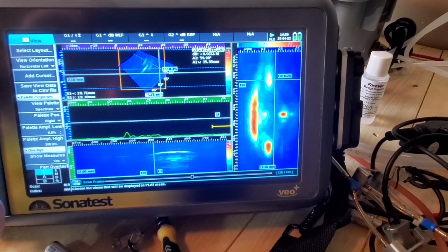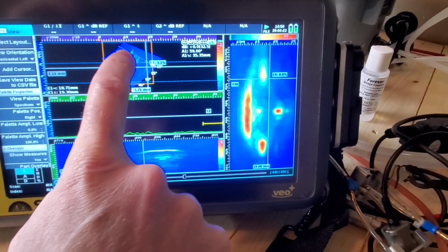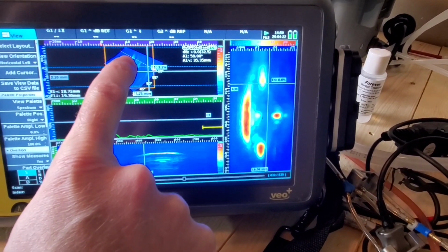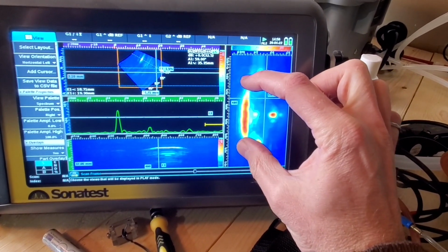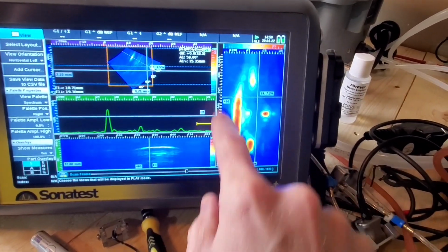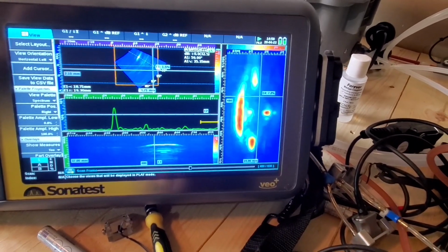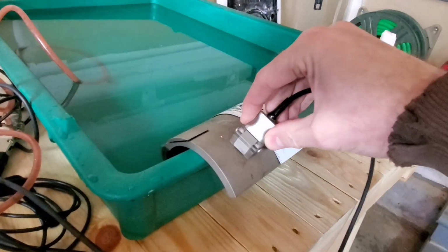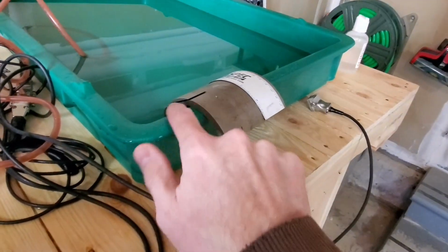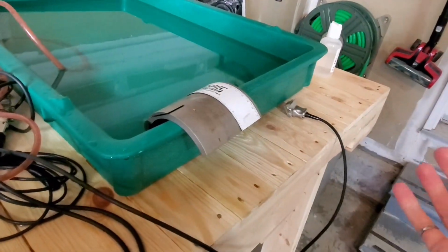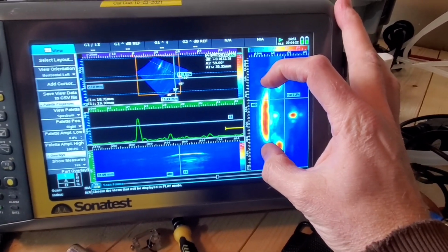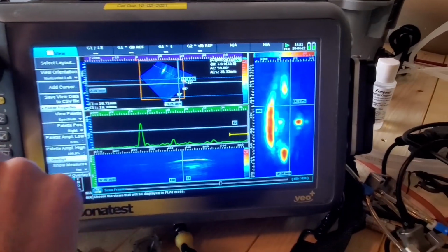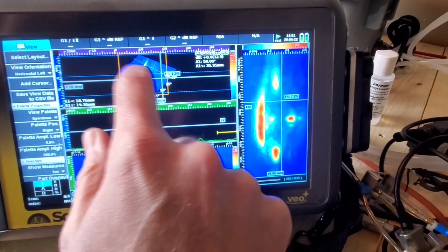So as I move the cursor throughout the scan, you'll start to see the actual signal from the hole itself start to appear. And the first thing you notice is, wow, it's really long. Mind you, it's a time scan, so don't bother looking at the millimeter markings on the axis. But you'll notice it's really long. And that's, of course, because when the probe is sitting here and the sound beam goes down to the ID and it bounces and spreads out, it diverges, right? So the beam becomes very wide. So the length of the whole peak is exaggerated after the first bounce off the ID.